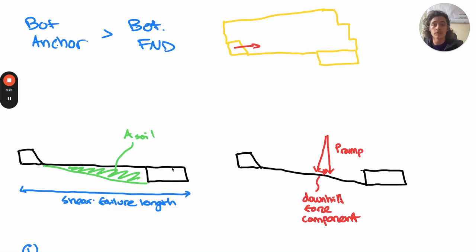Similar to how we use the bottom slope effects, which are in a different lecture for abutment sliding, to increase our sliding factor of safety, this configuration will result in a component of the abutment weight that is pulling the entire abutment downhill.